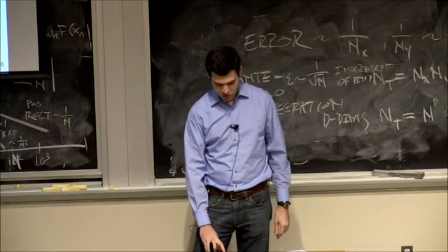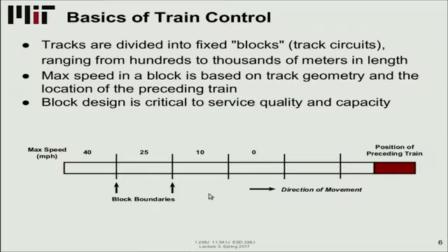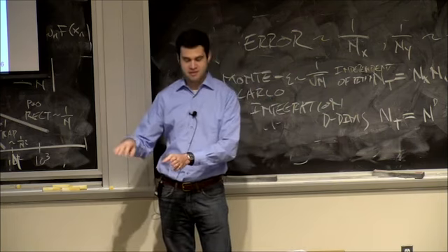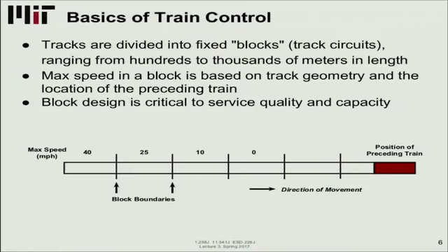And the goal of this system is to prevent trains from colliding with each other. So let's suppose that there's a train right here in maroon, and it's occupying a section of track. The track knows that a train is occupying that segment, and to prevent a collision, it blocks trains from entering the previous segment, okay? And how does it do that?